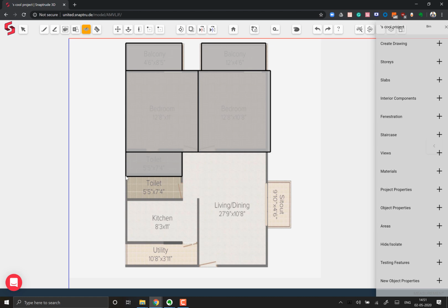Now I will use this anchor element of the vertex to draw another toilet 1200 mm along the blue axis, and I'll use this as my snap indicator to be able to do this. Now you can see that since I'm on the vertex, I can double click over here and complete the drawing. So if I double click, it will create a point over here as well as go back and join the origin of the drawing.